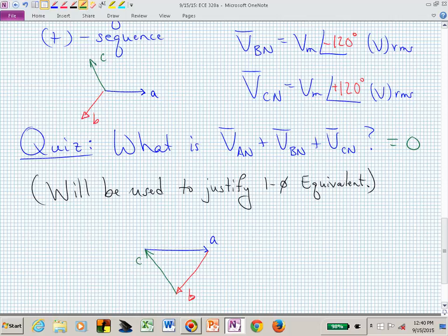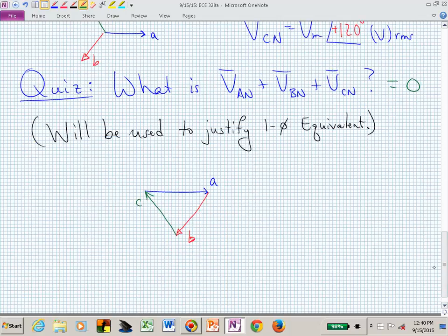And those, if it was Y connected, would be referred to, let's say the A phase was the voltage between the A terminal and neutral, V sub Bn is B terminal and neutral, etc. So N stands for the neutral conductor in this set of voltages. And here I was just using them a little bit more cavalierly. Here was V sub A, V sub B, and V sub C without a second reference point.